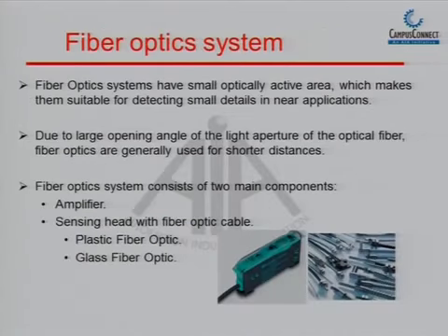Then there are certain fiber optic sensors. Again, the same concept: there is an amplifier and you have to connect a fiber to it. A fiber can be a through beam fiber or a diffuse fiber. There are different types of fibers, plastic fiber and glass fiber. A glass fiber generally has a metallic lamination on top of it, so it can withstand high temperature. A plastic fiber cannot work in high temperature areas. Concept-wise it is similar to what a diffuse or a normal photosensor would do.